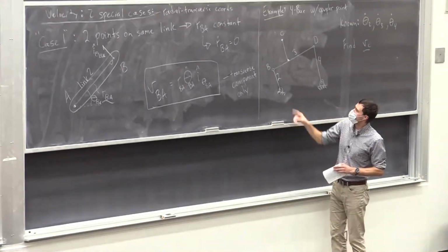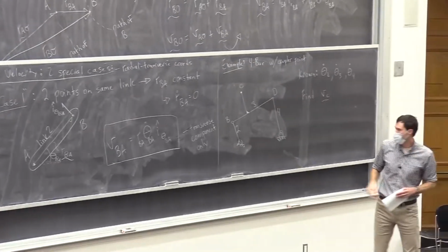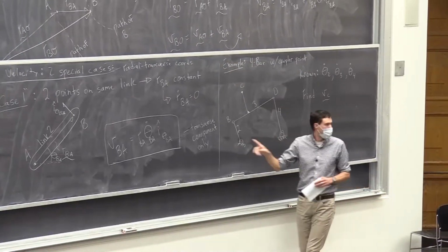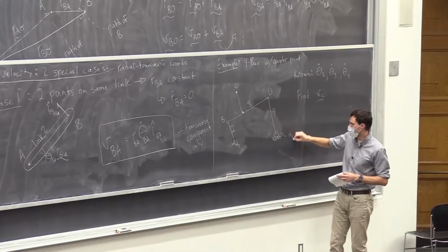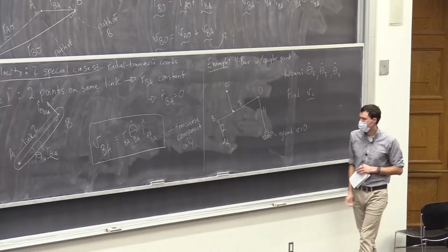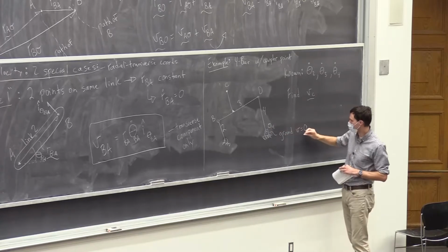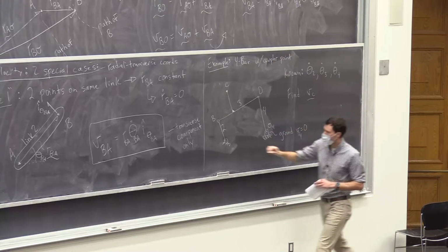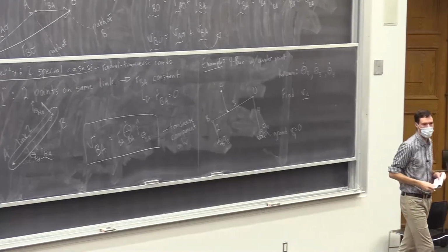Okay, we see that we have 2 ground connection points. So for velocity analysis, we're always going to start at one of the ground connections somewhere, because we know the ground has velocity of 0. So I could name these points like O4 and O2. Different ground origin points.